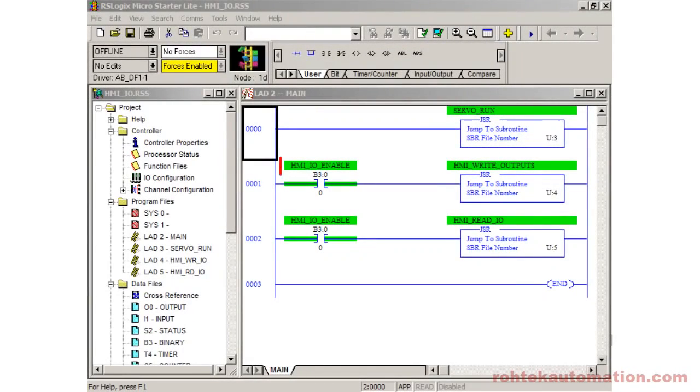The PLC program can, for example, implement an HMI enable bit whose value could depend on things like completing a startup sequence, the current COM status, or various safety checks. By the same method, the PLC program can referee the HMI's reading of data, particularly I/O, ensuring its validity prior to enabling HMI access.